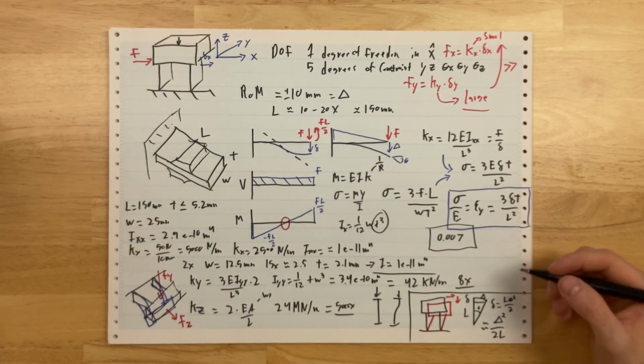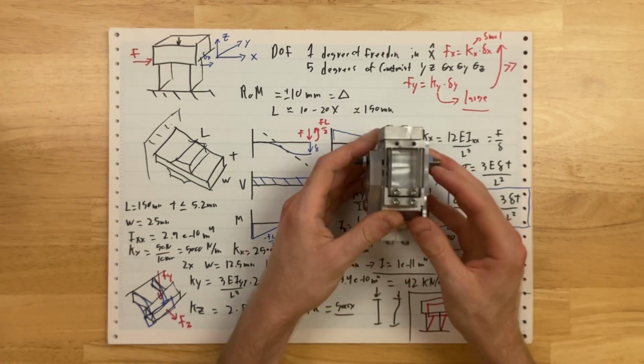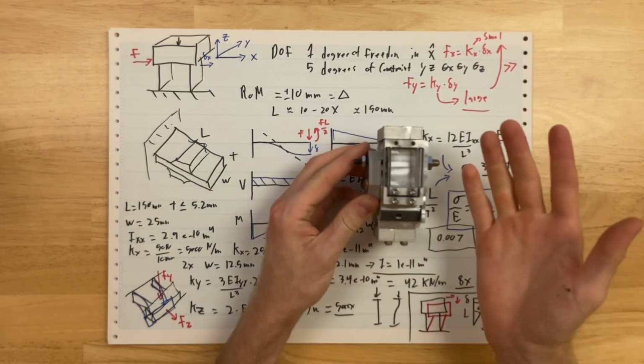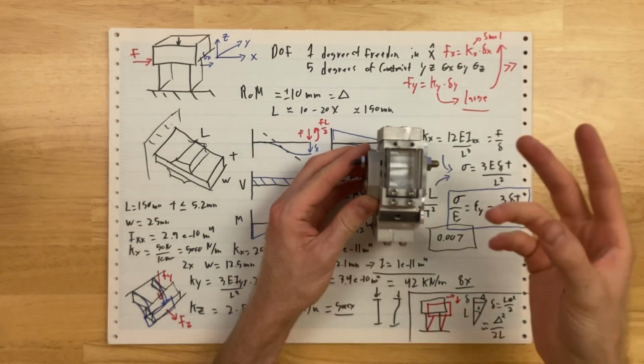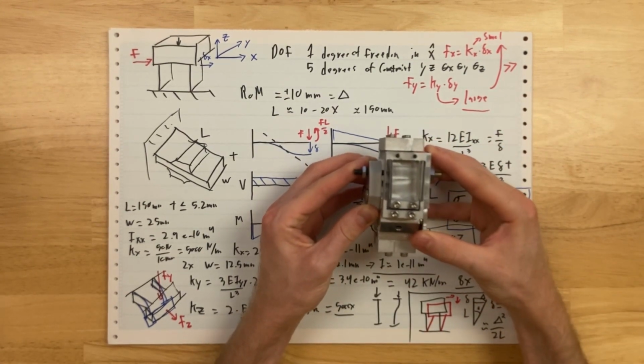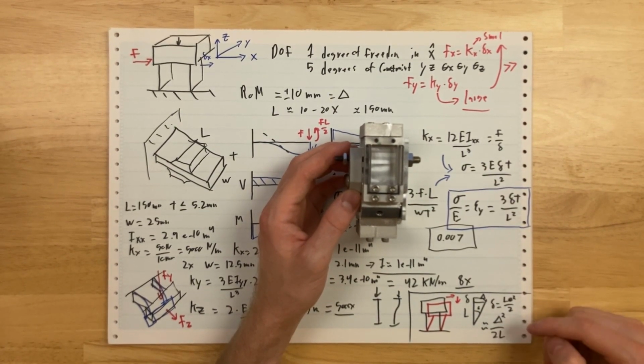So how do you account for that? Well, that's where you invoke the double parallelogram. If you have two of these systems that have the same stiffness and move the same amount, one will foreshorten in one direction while the other moves in the other, and it basically counteracts. So by use of symmetry, you can get a system with basically no foreshortening to first order.